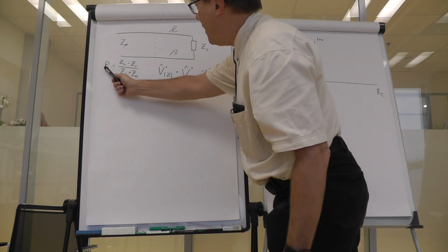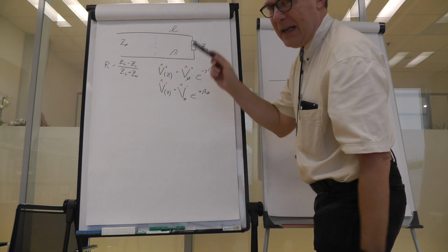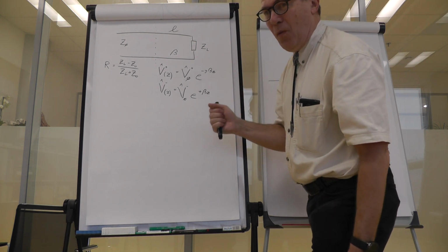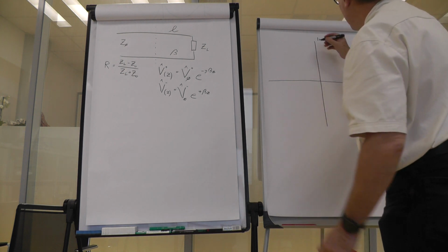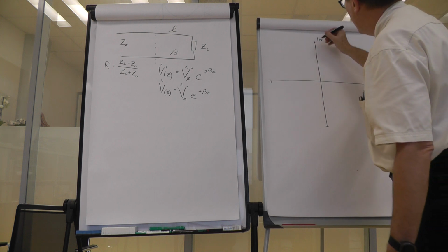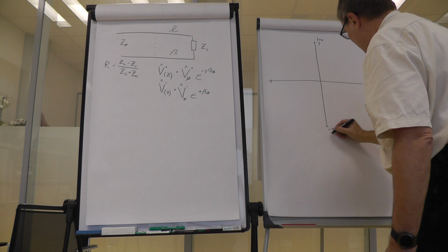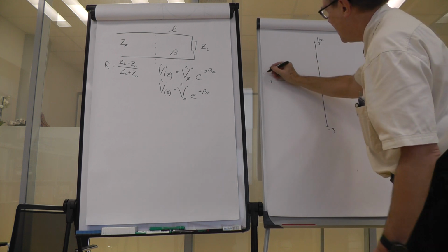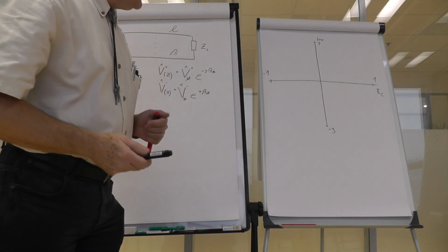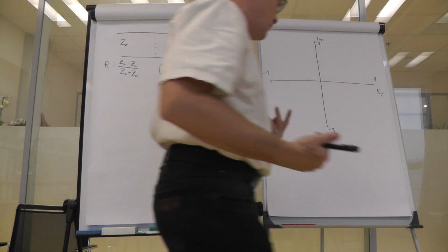So this coefficient, the reflection coefficient, sometimes also denoted as big gamma, is at maximum 1 in magnitude. So we possibly would be somewhere in the region where this is j, this is minus j, this is 1, and this is minus 1, the real axis. Somewhere bound in there, we would have all the values of possible reflection coefficient that could be achieved by passive loads.